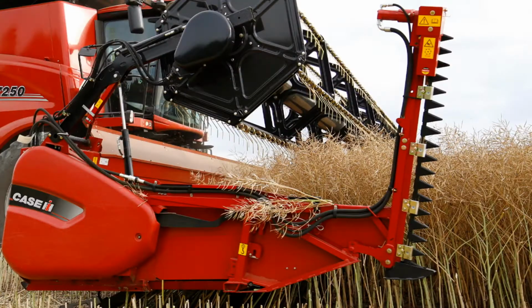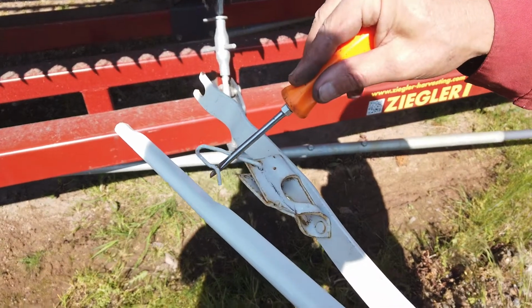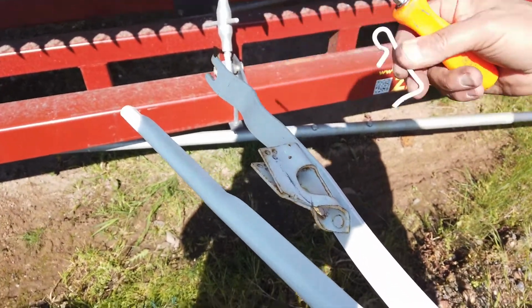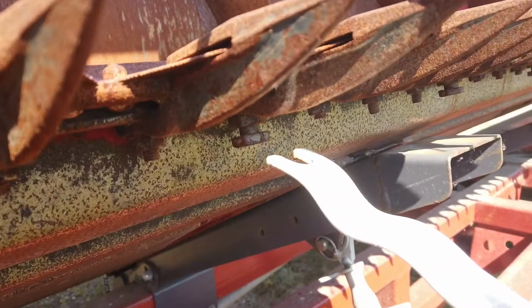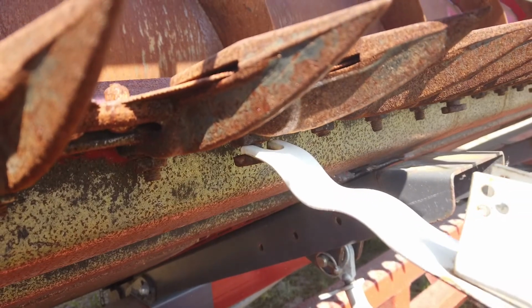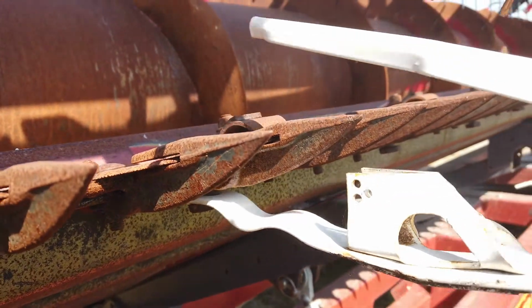Be careful, they are heavy and sharp. The left-hand knife has a hydraulic feed and return coupling. The right-hand knife has feed, return and a case drain coupling. Connect accordingly. A set of crop lifters for every 4th finger is supplied. These can be fitted for crops such as necked over barley, peas and stony conditions.